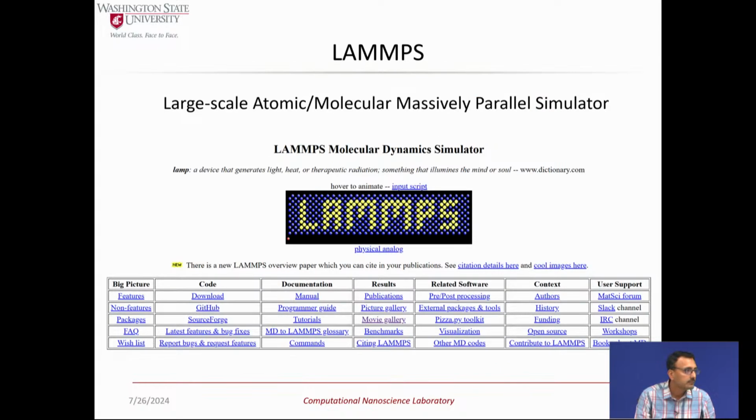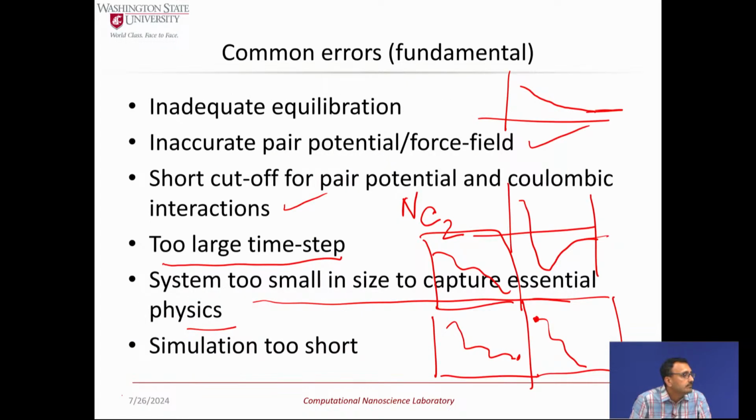There are more than 2 atoms interacting. Like there are three-body interactions. And you are considering 2 atoms interacting. If there are 3 atoms interacting together. Not necessarily. There are potentials that are many-body or multi-body potentials. For example, the Tersoff potential, Finnis-Sinclair to a certain extent. So not all potentials are just one-to-one. There can be an angular term. For example, even in the MEAM potential, there is a term.